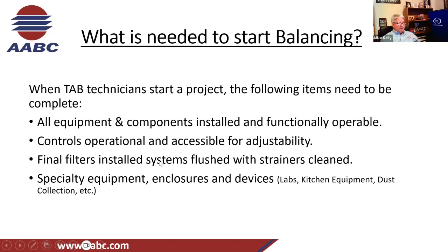We need filters installed and systems flushed with strainers cleaned. Strainers and filters are in the same line, just different systems. And you shouldn't be balancing air handling units with dirty filters. You never want to be balancing water systems with dirty strainers.